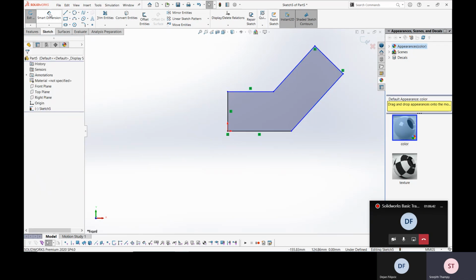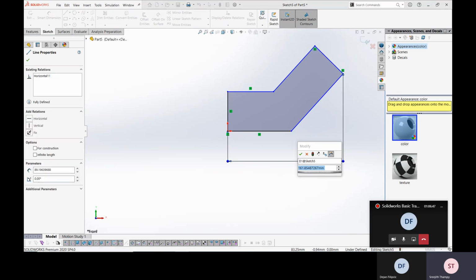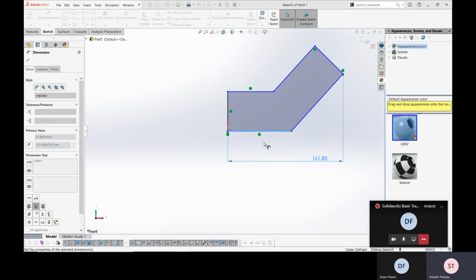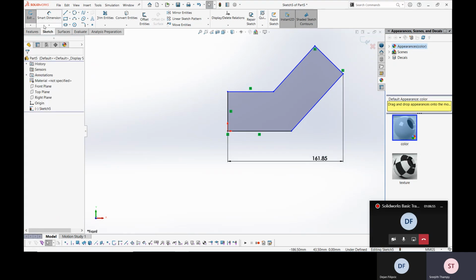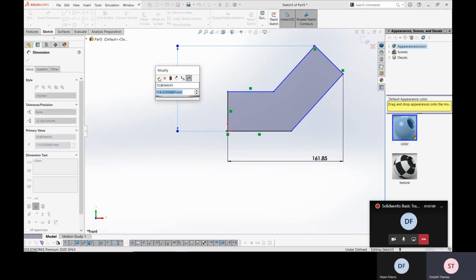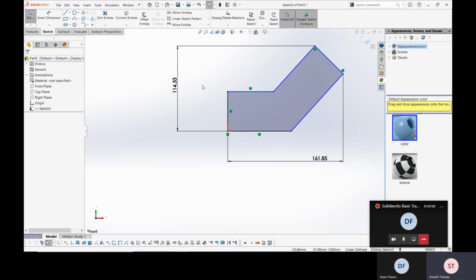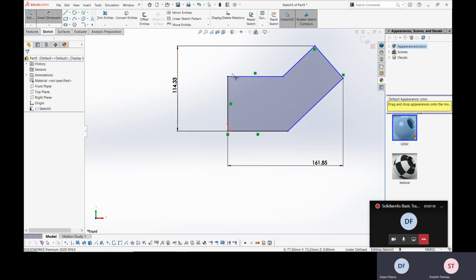So if I give something like this length should be this much, and this length should be this much, this is not enough for someone to manufacture this. In the physical sense, that is the meaning, that you are not giving enough information to get this thing created, or it can be changed. So with these two dimensions being the same, the shape of the sketch can change in multiple ways, right? That is underdefined.